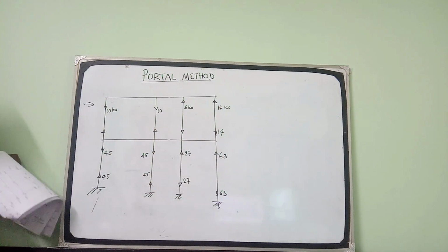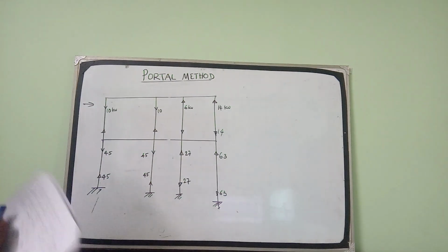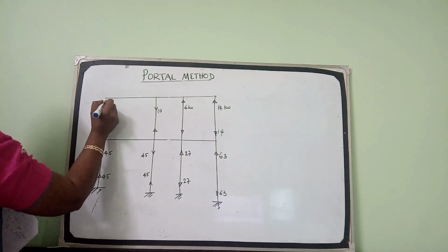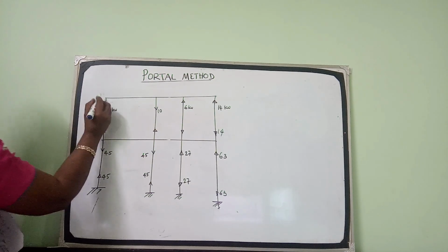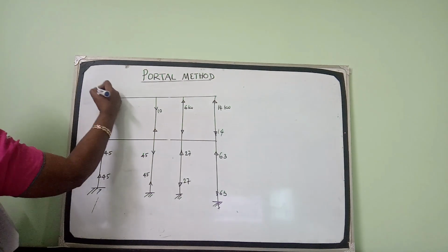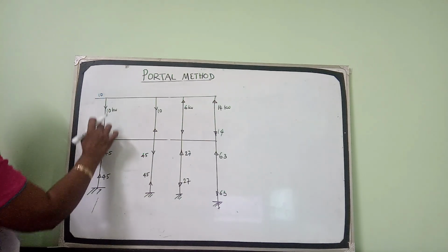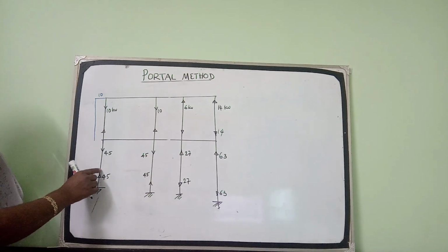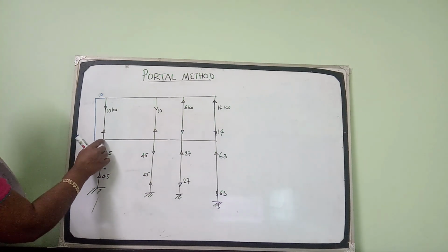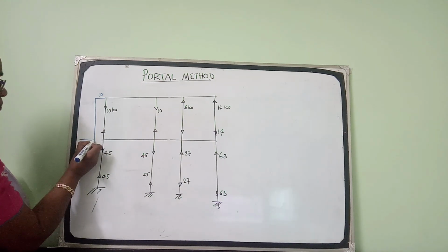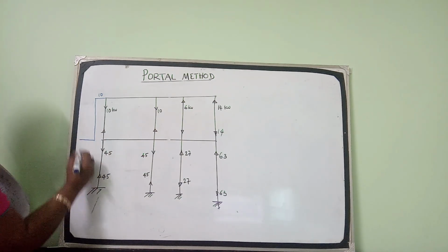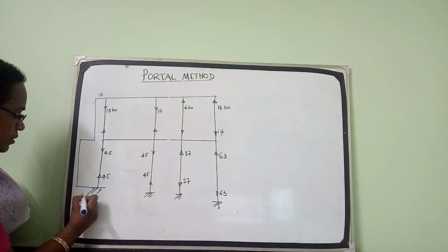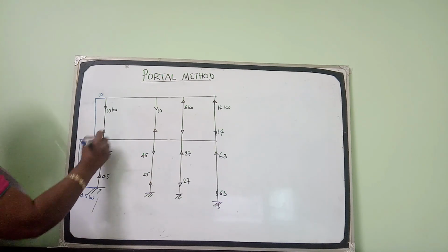Now how to draw the axial force diagram? So here, this is subjected to 10 kilonewton tension. So I will draw on the left side. To some scale, I will mark 10. Up to this, there is no force. We'll mark it 10 kilonewton, this entire column. Then suddenly, this column is subjected to 45. So from here, you mark 45. So here to here, it is 45. Then here, completely 45. So this is the axial force diagram for this column.